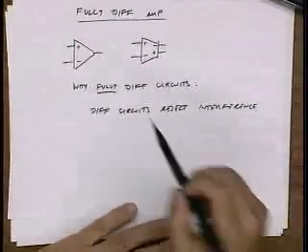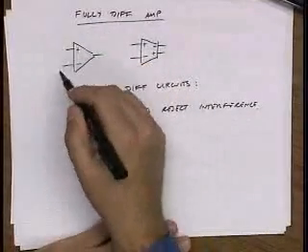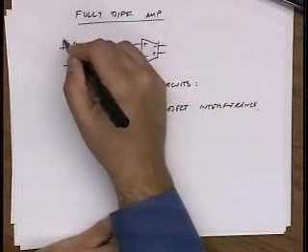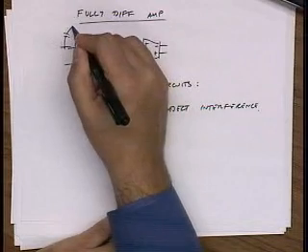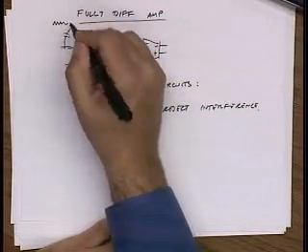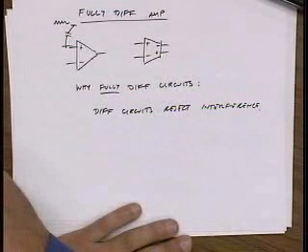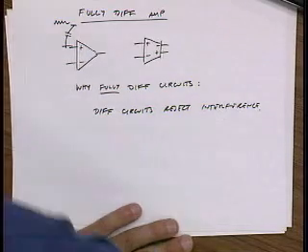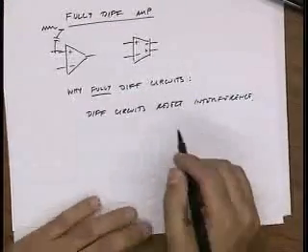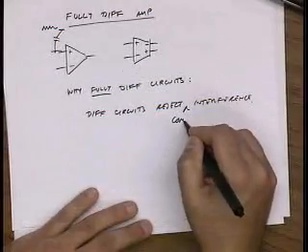Let's say I have an amplifier here, and unfortunately there's a capacitor from this node to the power supply. Let's say my power supply is dirty. Is this amplifier going to reject this? No? Why not? Yeah, it's got to be common mode noise. So it rejects common mode